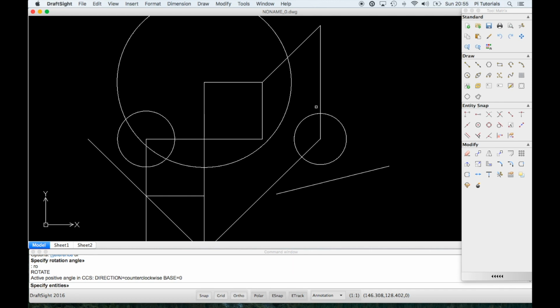I'm pretty sure we could do a rotate and copy. Maybe I've gone wrong; I thought I could copy. Anyway, let's do a copy command. CP is for copy. Specify entities, and we can again use our crossing selection. Once they're specified that we want to copy, space.